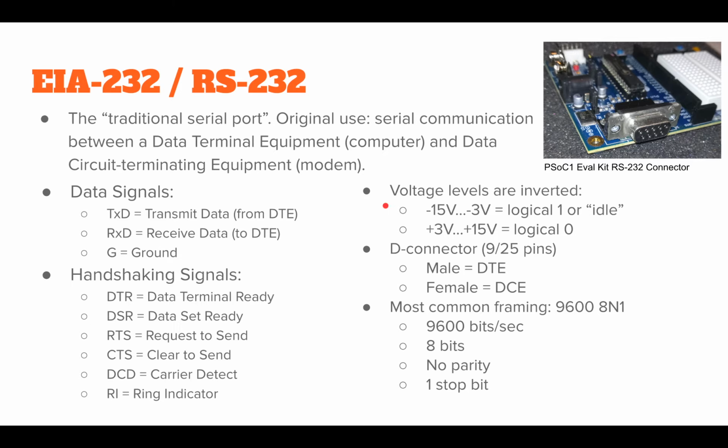Voltage levels are inverted: logical 1 or idle is actually a negative voltage, and logical 0 is positive voltage. Okay, and as you can see, this is not even TTL compatible, although most of the modern RS232 bus drivers actually do work also on TTL level signals.